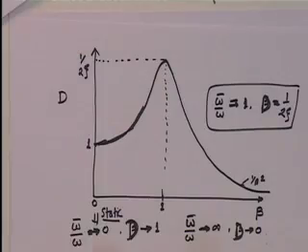So, if omega, let us say, is 0.1 hertz, then omega bar is 5 hertz or even 1 hertz. Now, you would say that omega bar of 1 hertz is not a very high frequency, but relative to the flexible structure, because 0.1 hertz is a 10-second time period, it is a very, very flexible structure.